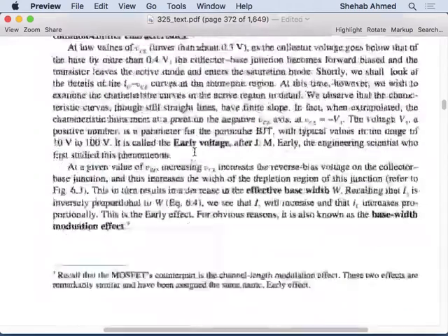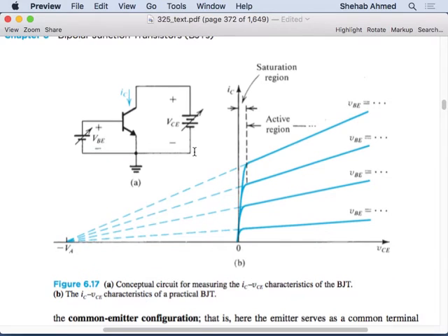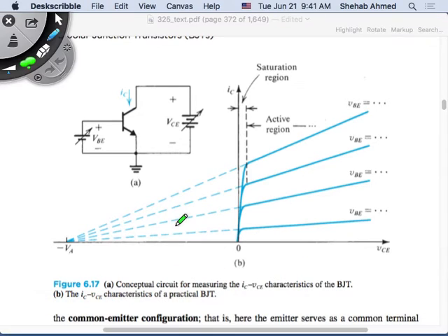The slope of this line, this is what? This line is changes in current versus voltage. So delta Y is current and delta X is a voltage, right? The slope of this line, delta Y over delta X, is a current over a voltage, which means it's 1 over a resistance, right? So which means that I can sort of model that in my equivalent circuit. I shouldn't have erased my equivalent circuit. Do we have to increase the voltage?